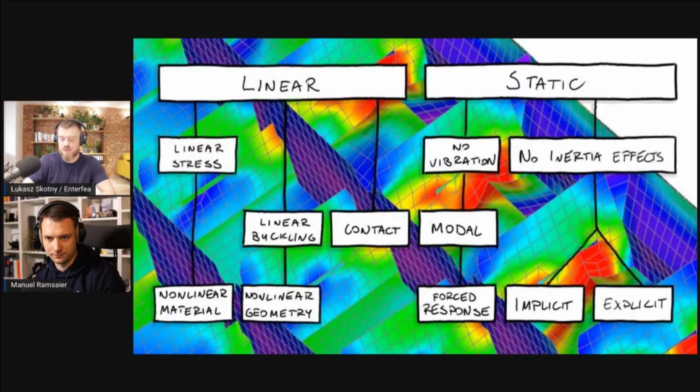So linear buckling allows you to calculate a critical force or critical moment, depending on the load you applied in your beam. And then there are like 1-2 equations. So you input the critical moment into one of them, you get slenderness, then you calculate the capacity, and bam, you have the real capacity. It will always be lower than the critical. Yeah, sure. Oftentimes very much lower.